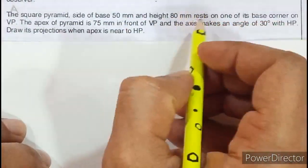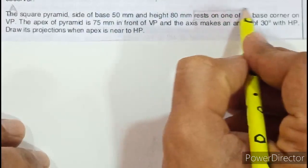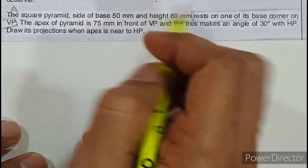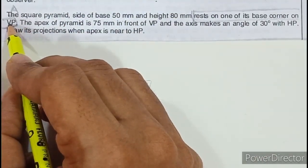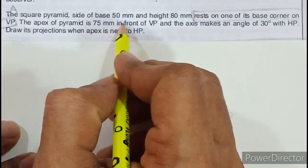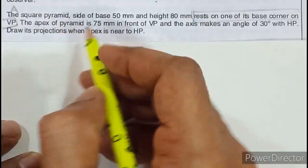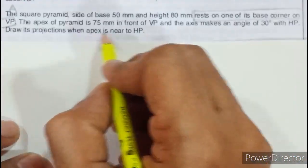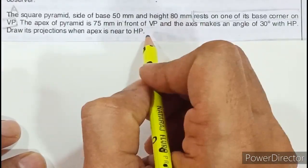As we have discussed, the resting condition is always the first stage. So it's clear that rest on one of its base corner on VP is our first stage. If the first stage is with respect to VP, the second should be compulsory with respect to VP only. So the apex of the pyramid is 75 mm in front of VP is the second stage. And last, the axis makes an angle of 30 with HP and apex near or apex away is the third stage. So VP, VP, HP is the condition for this question.